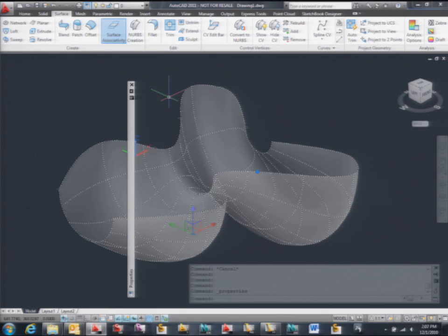So my suggestion, I've been modeling a while with these things: just keep explicit surfaces as much as you can. If you really hit a place in which you need to make extra changes that are not within the creation process of that entity, do whatever you want, go to NURBS. But in the meantime, keeping explicit surfaces allows you to have a lot of flexibility.